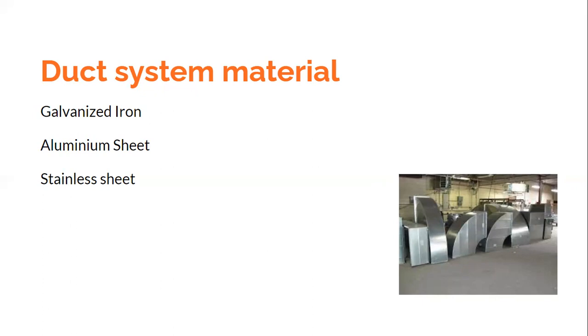The resistance is also offered by the cooling coil, the air washer, if it is an air washer type of system, the filters, the dampers, etc. Along with that, if the ducts also offer resistance, then the fan has to work against that head. As the head, that is the pressure to be overcome, increases, the fan would require higher power consumption.